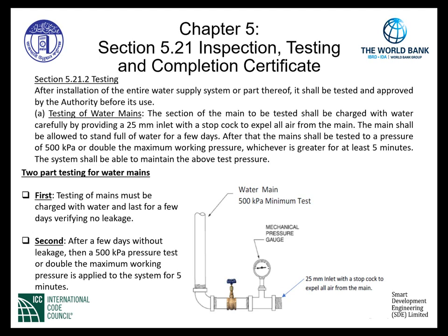We have to charge them with water, let them last for a few days, just verifying no leakage under that static pressure. Second, after a few days without leakage, we must provide a pressure of 500 kilopascals or double the maximum working pressure. Apply that to the system for 5 minutes and observe if there is any leaks in any joints, parts of the piping, things of that.